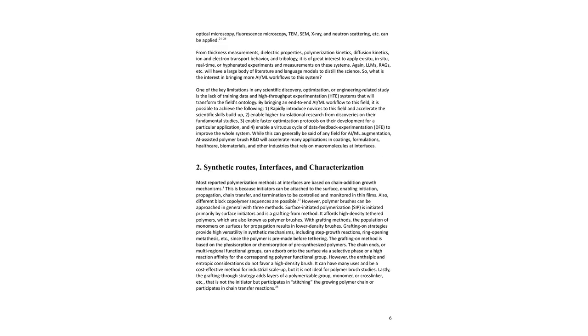Now, how do we create these structures? There are generally three main strategies for attaching polymers to a surface. The first, and perhaps most common for creating high-density brushes, is the grafting from method. Here, initiator molecules are first anchored to the surface. Then, monomers are introduced from the surrounding solution or gas phase, and the polymerization process is initiated directly from these surface-bound sites. The polymer chains grow outwards from the surface.